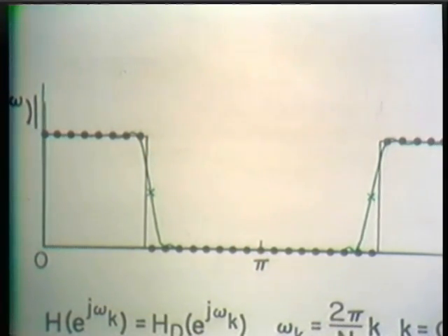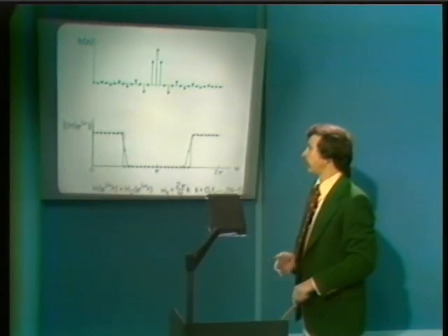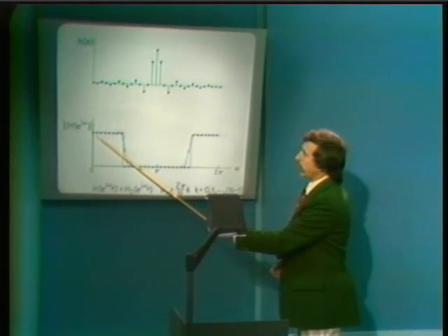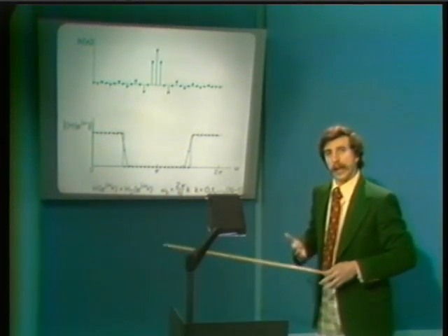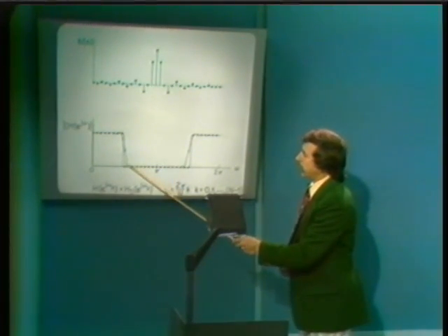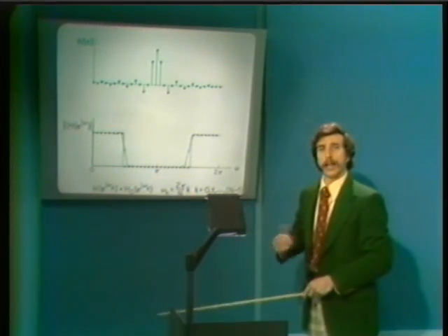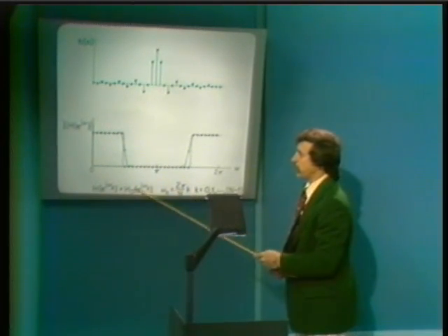So this in fact is a design technique that can be used for the design of generally band frequency selective filters, where we first of all specify frequency samples. In fact, this can be used really for the design of any digital filter characteristic with transition regions, and then perhaps reducing the ripple in the passband and or the stop band or in the various bands by allowing an additional point to be used to widen the transition band.